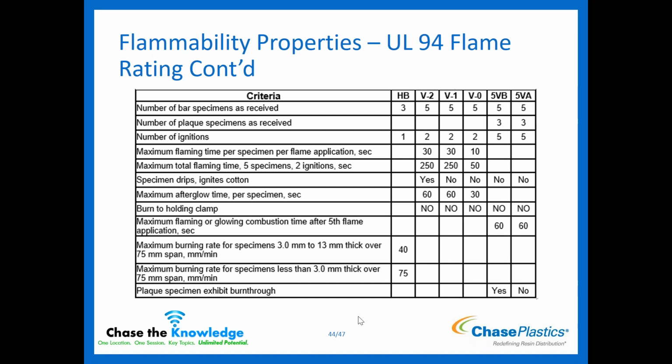So something to consider when you are asking for a specific flame rating for your material, do make sure to mention what thickness you need, because it doesn't do anyone any good if you have, let's say, a 0.5 millimeter part and you need to be V0. Well, if I'm making it out of this Ultem, the Ultem's not V0 until 0.75 millimeters. So at 0.5, we're not going to have the rating you're looking for. So it is good to know the flame rating and what you need and what's expected, but you also need to understand the thickness of your part so we can make sure that we're matching that specifically to your needs.